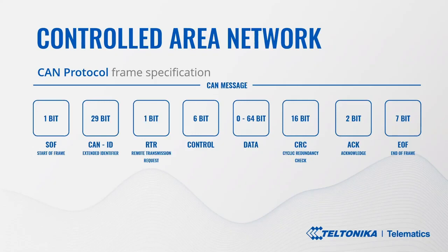However, each network node has a unique identifier. Different parameter IDs may be used. There are also differences in data byte order, offset, signal count in one message, and other differences. Therefore, in order to be able to decode the data that is being sent and read the parameter values from different type of vehicle models, it is necessary to perform reverse engineering tasks.